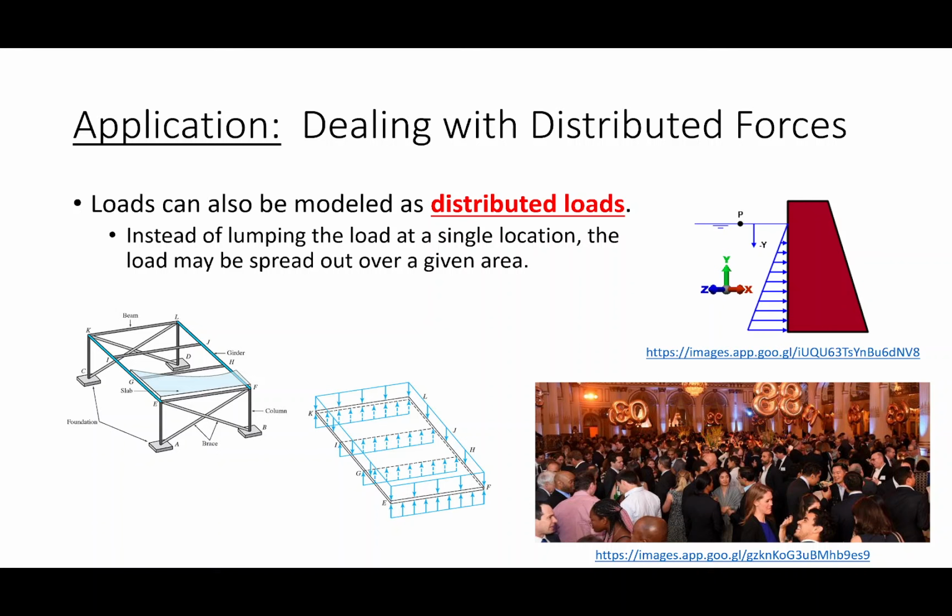So how that would come about on a given beam or a given element in the structure is, the element in the structure wouldn't see a 200-pound force or a 2,000-pound force right in the middle of the structure. It would see a load distributed across its length. Okay? So we wouldn't be dealing with a single point load. We would be dealing with a distributed load. Okay? Now there are applications of distributed loads in all areas of engineering.